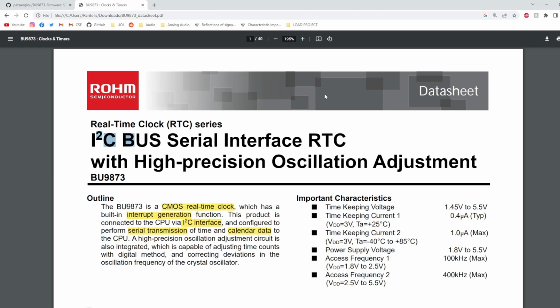Next thing that you have to go through is the pin description section that gives some info about the pin configuration of the peripheral, and also to take a quick look at the electrical characteristics, because this might change the way the peripheral operates. Once you do all this, then you have to take a quick look at the interface information, because it might share some details for the peripheral interface that differ in operation compared with other applications in other peripheral ICs.